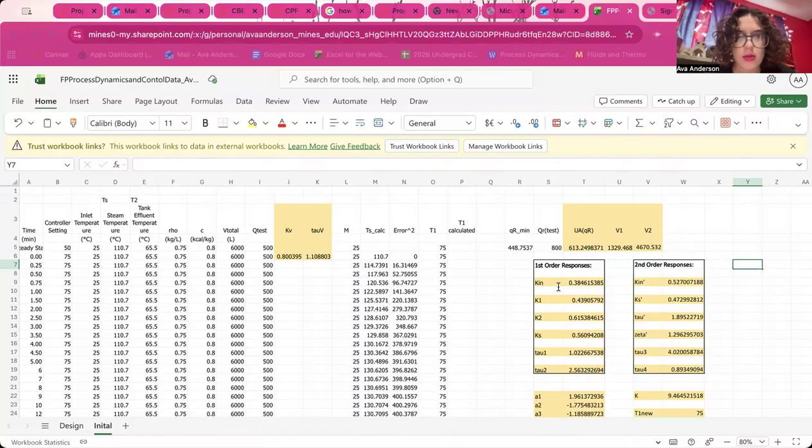Okay, so I am talking about the project. It's a dynamic analysis that was conducted on a poorly mixed heater tank to evaluate its ability to operate under PI control at design conditions. The tank does not behave as a single well-mixed system, therefore we're modeling it as two continuous stirred tank reactors with an internal recycle loop.